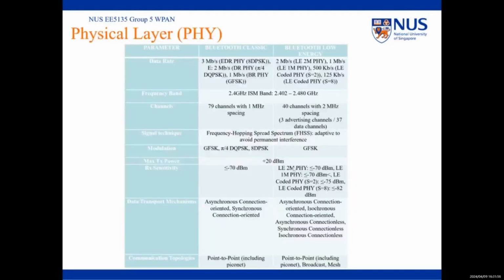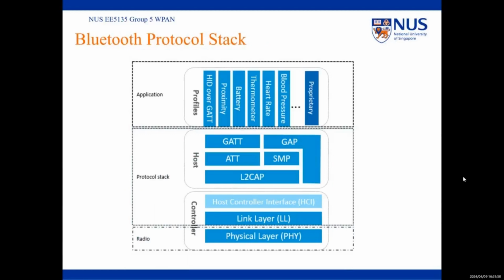And then is the host controller interface, HCI. HCI is optional. HCI is mainly used when two chips implement the BLE protocol stack, to standardize the communication protocols and communication commands between the two.